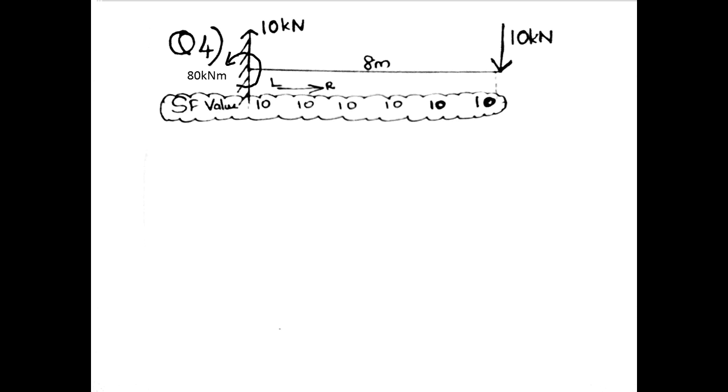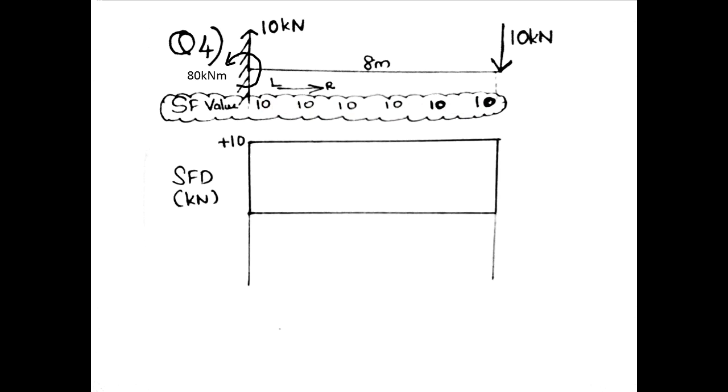These are the shear force values. Consider the left to right technique. Therefore upward force is positive. Here plus 10. There are no loads, therefore 10, 10, 10 up to here. This is the shear force diagram. Plus 10.